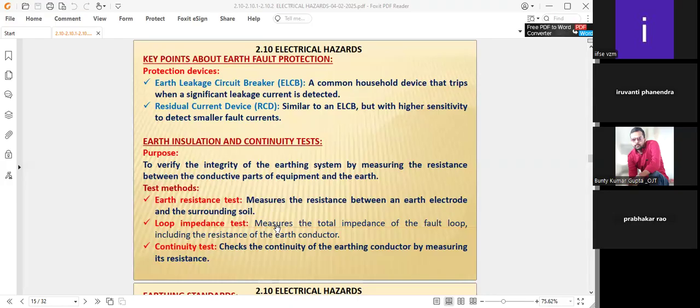During that time, you have to see that the current is off, make the earthing facilities proper, and see that the resistance of the earth conductors works properly. What we have to see is that the earth has zero potential, earth potential is zero voltage. Therefore, all the leakages should go to the earth only. Therefore, saving of the employees, saving of the equipment, saving of your appliances like MCC and MCP, and equipment damage also will be controlled.